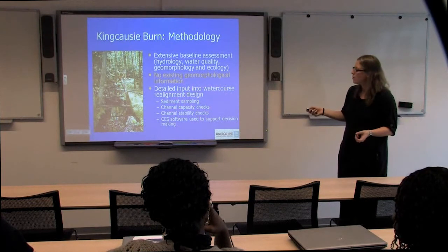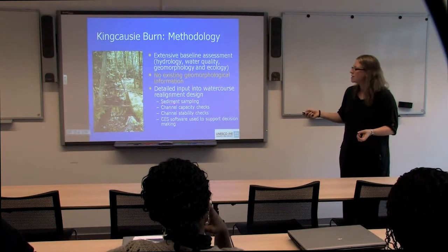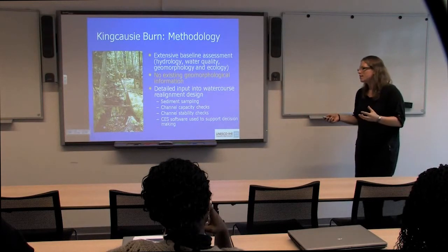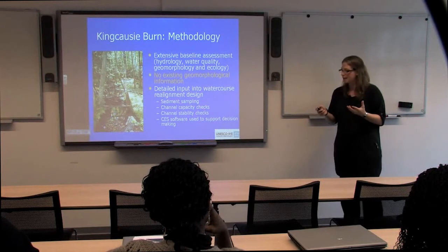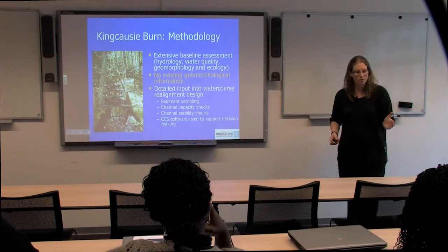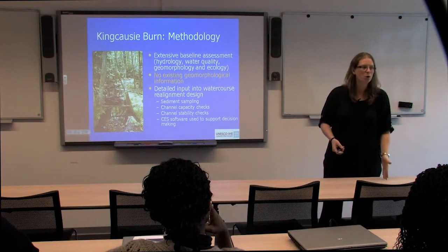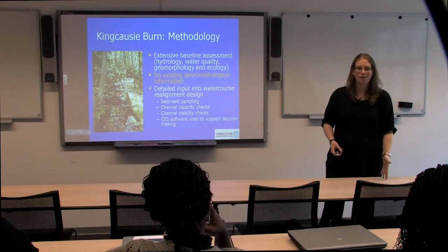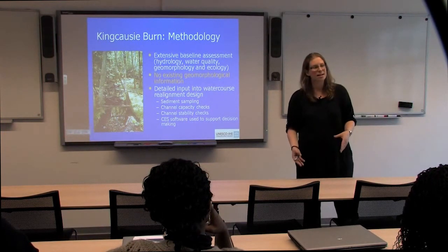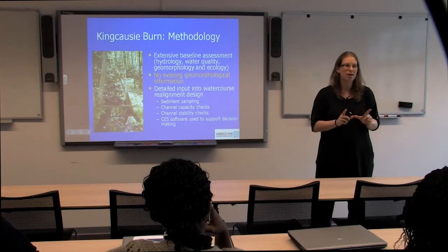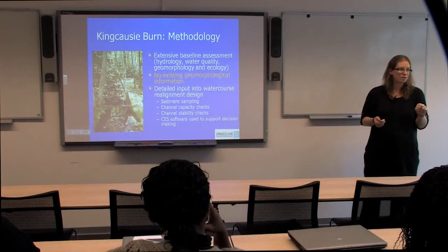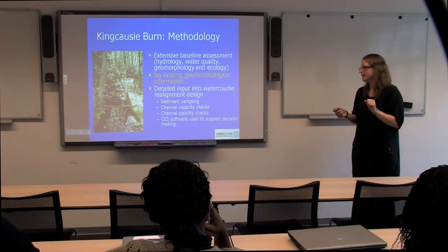So when we went to look at the design, we could use this sediment sampling from what we knew was existing, and we could use that in our new design. We also used something called the CES software. This is a particular situation where the river's smaller, so we don't need to use a three-dimensional model or a two-dimensional model. Here, what we've done is simplify it down to look only at cross-sections. And here we're applying Manning's equation at the cross-sectional space scale.